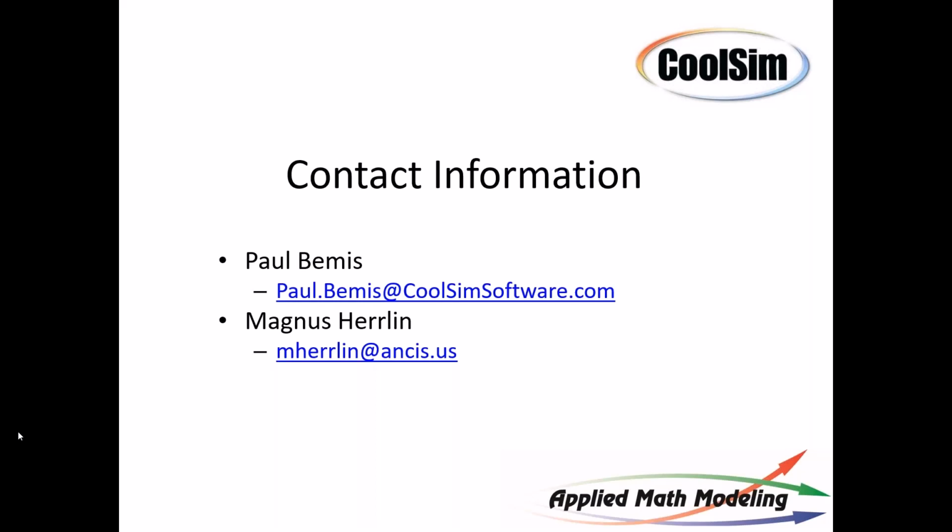MLC is going to be much better, but it hasn't caught on. MLC just compares the energy to cool the data center to the energy required to drive the IT server. So you're getting more of a one-to-one, direct comparison of cooling energy to IT load energy. When you make a small change in MLC to things like fan or leakage, it will show up pretty quick. But PUE, because it's got IT energy in the numerator, the number doesn't change very much, unfortunately. But it's better than nothing.